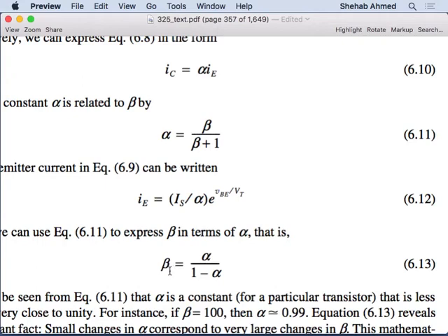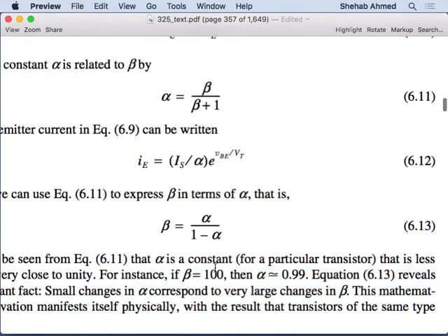We will find that in practice, beta is highly affected by the manufacturing process. So you will be given a device with beta in a huge range. Beta will not be a nice fixed variable. Beta equals 100 is an ideal number to consider, but in reality it's a very big range, because it's highly affected by the manufacturing process. Okay.